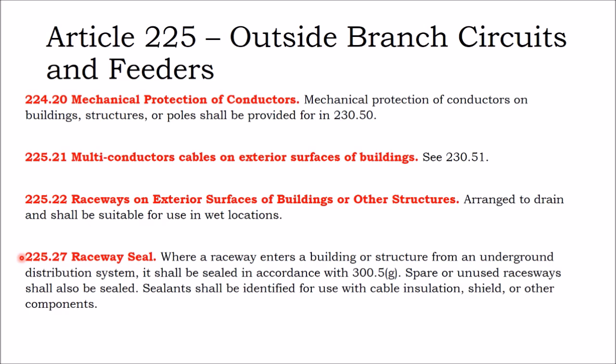And from the line side tap, we just went up straight into the soffit of the attic. Well, the humidity and the heat difference between that underground utility service entrance run and then going through the outside porch up into the attic was enough to cause a puddle of water to occur in our junction box where we made the line side tap.